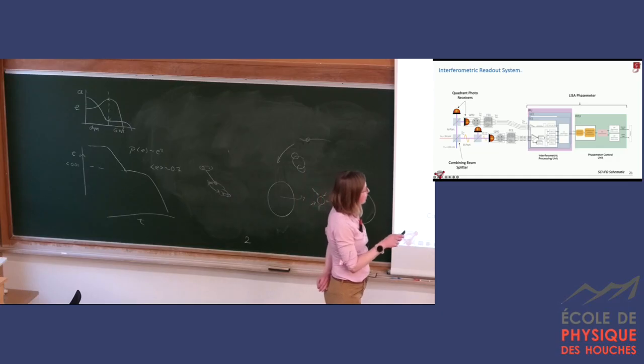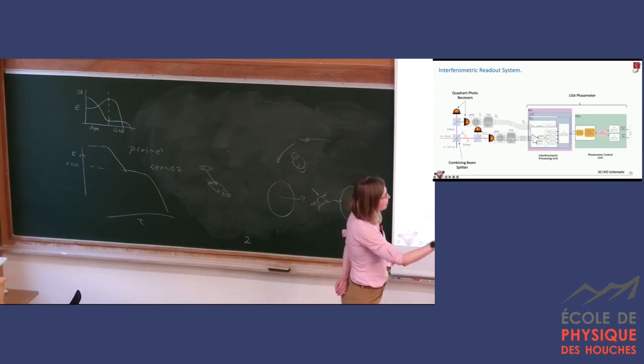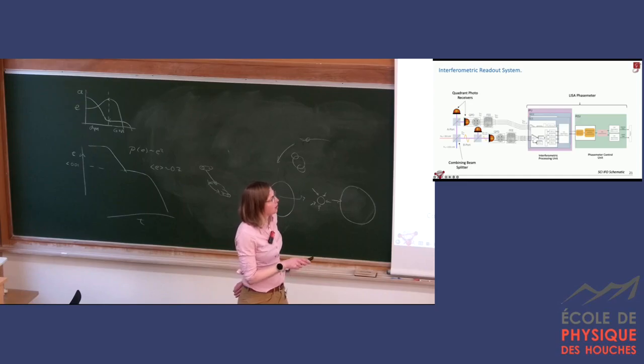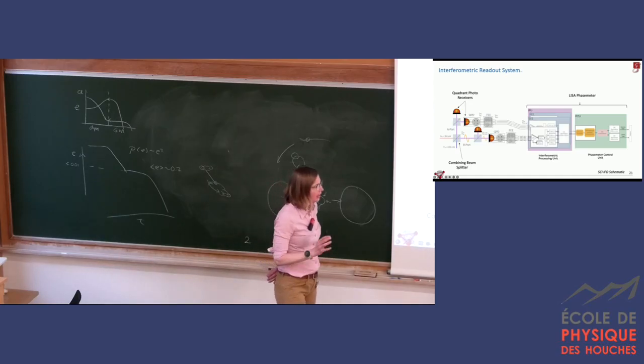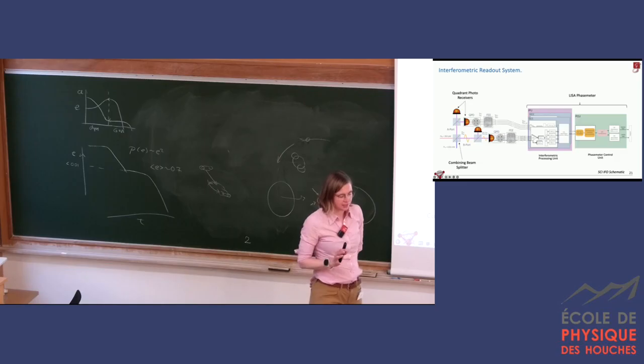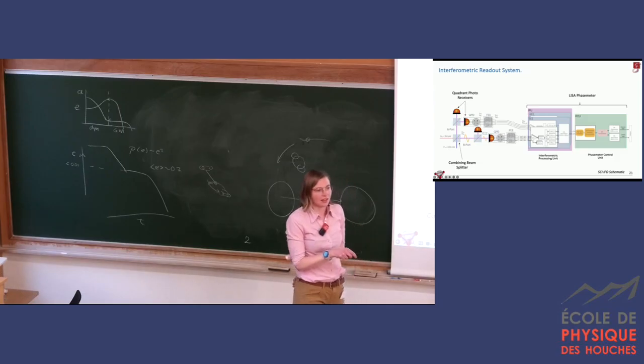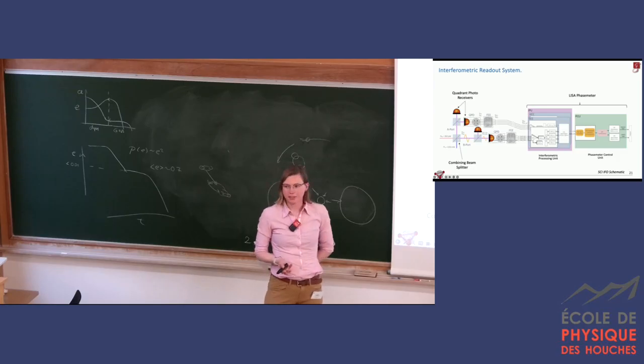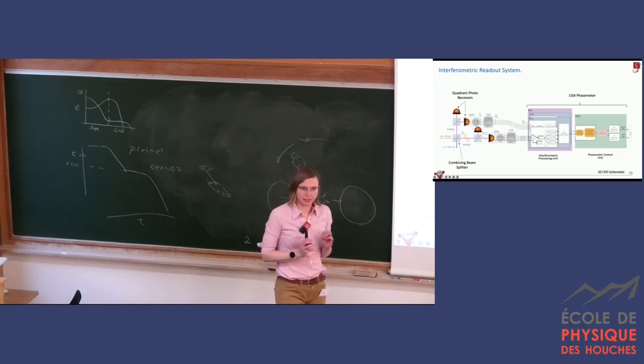Each of them sends the signal into the LISA phase meter that actually extracts the phase information and provides other functions that are necessary for the constellation and TDI. The LISA phase meter is built out of two boxes, roughly. The reason is very pragmatic. That bit is very sensitive to temperature. It has analog electronics and analog-to-digital converters. And that bit consists of the power supply unit, and they don't like each other very well.